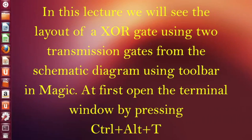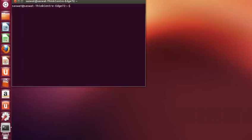In this lecture, we will see the layout of a 2-input XOR gate using 2 transmission gates that is drawn from the twisted schematic by using the toolbar. In order to open the terminal window, press Ctrl Alt and T, then type magic, press enter.